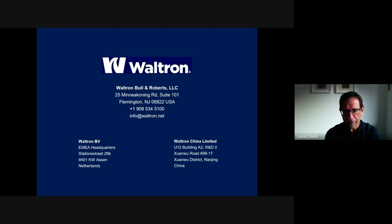They are definitely in favor. Total cost is definitely in favor of the luminescent technology, not really because of the price of consumables and replacement membranes and all that sort of thing, but consider the labor that is involved in exchanging the membranes, taking a sensor out of service, and also considering the amount of time where you're offline with that measurement, and again, creating that blind spot that we were supposed to eliminate with the measurement.